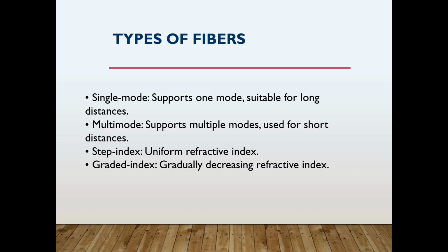They are also lower cost. MMF is generally cheaper to manufacture and install because the components, like the light source, LEDs, are less expensive. Another advantage of MMF over SMF is that less precision is required. The larger core diameter of a multimode fiber allows for easier light coupling from the source.